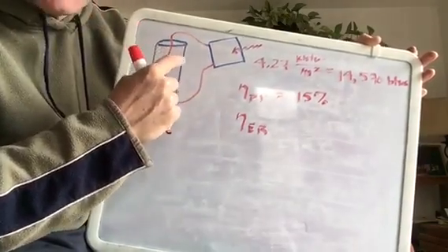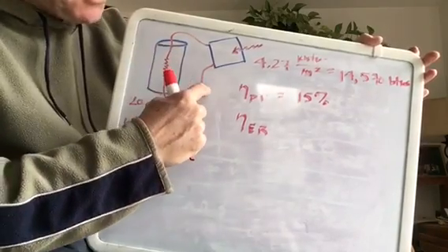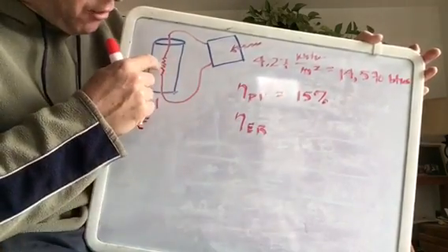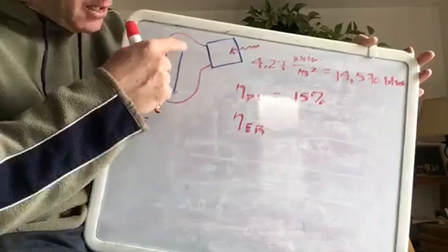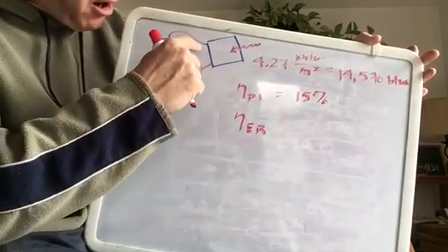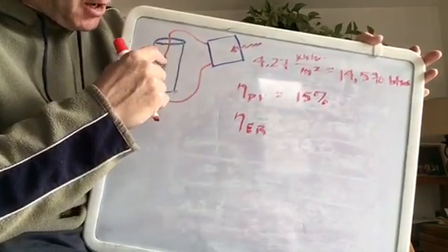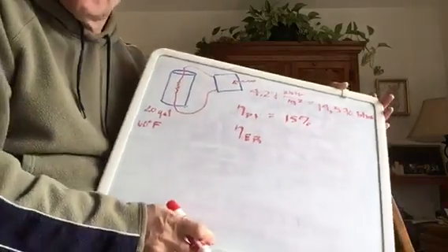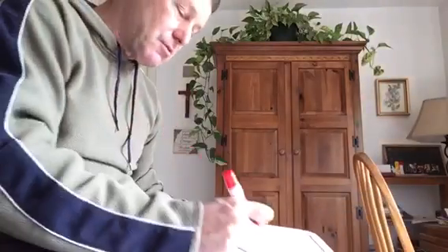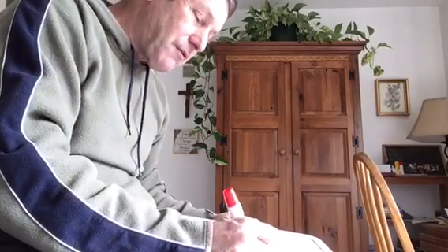Wire has minimal resistance, so only a little bit of the heat is going to go in the wiring. All the heat is going to occur right there like that. And if you have this tank well insulated, almost all the energy that's in the wire is going to get into that water. So the efficiency of electric resistance water heating, let's use 98% for our number.